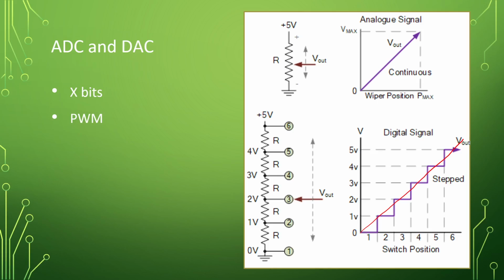But anyway, analog to digital converters, ADCs. They are rated, I'm going to use the word rated, it's probably not the proper term here, but they are rated in how many bits they are. So if you have a 0 to 10 volt range, we're just going to stick with that, this makes my life kind of easy, and you use an 8-bit ADC, you have 256 steps in that range. So that means from 0 to 10 volts, you would have 256 different steps.